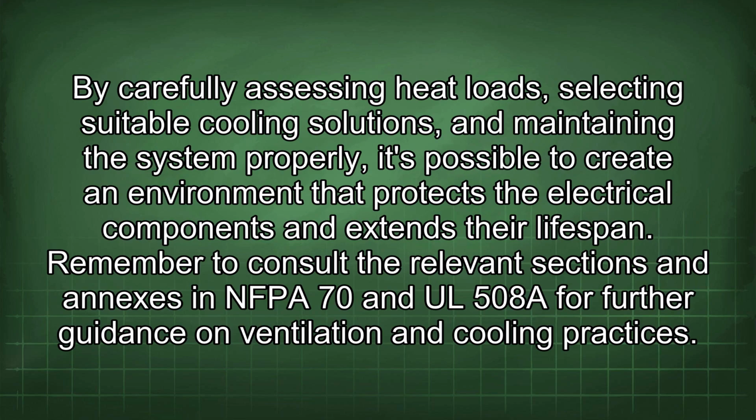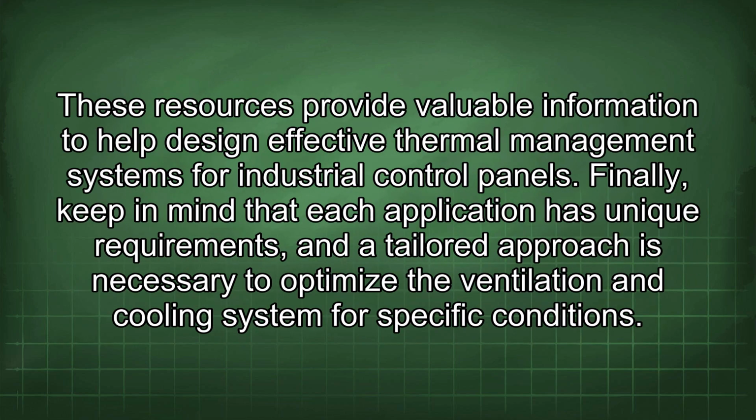By carefully assessing heat loads, selecting suitable cooling solutions, and maintaining the system properly, it's possible to create an environment that protects the electrical components and extends their lifespan. Remember to consult the relevant sections and annexes in NFPA 70 and UL 508 for further guidance on ventilation and cooling practices. These resources provide valuable information to help design effective thermal management systems for industrial control panels.